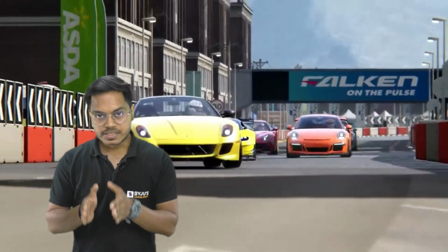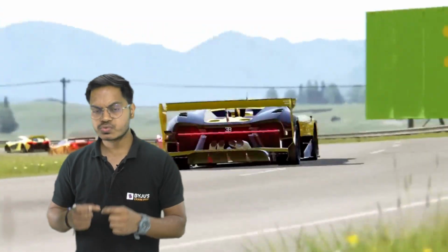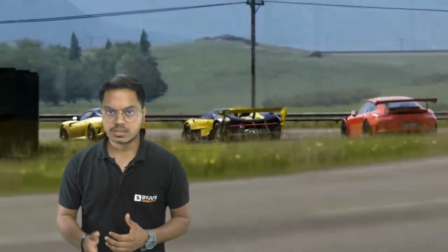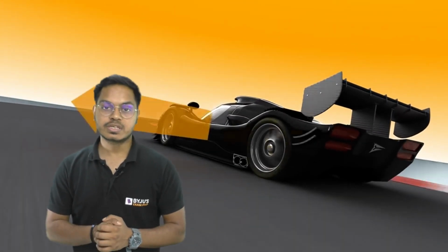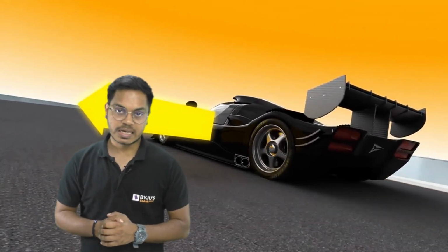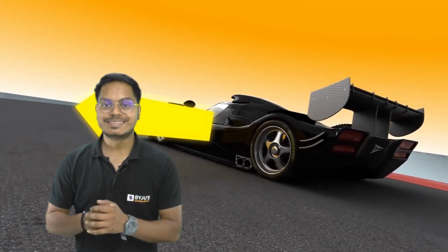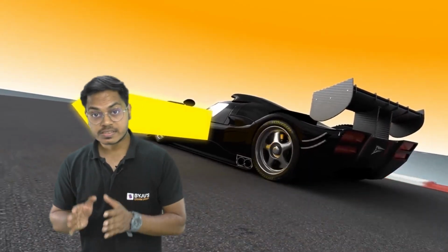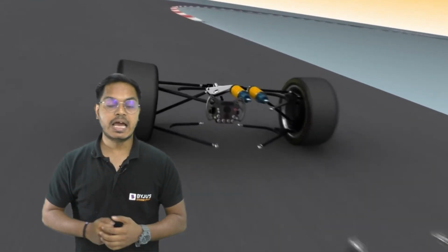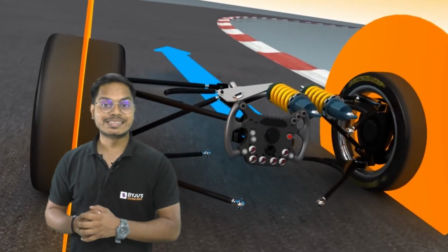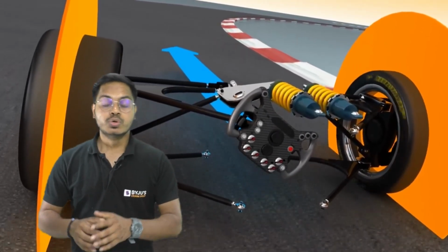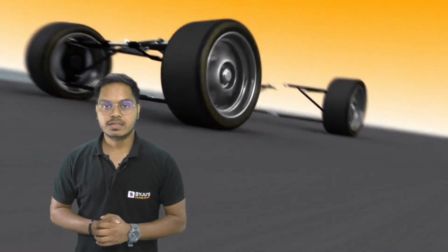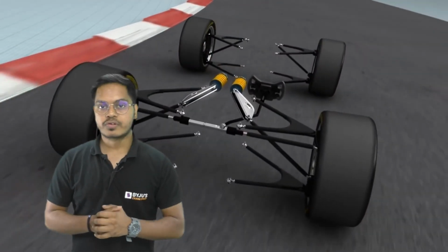क्योंकि जैसे ही कोई भी कार, as soon as any car takes a turn, whether left or right, it actually experiences a force, and that too opposite to the center of the curve, and that force is called the centrifugal force. Now this centrifugal force has the intensity and the capability of either skidding the vehicle to the outer side of the curve, or, you can say, overturning the vehicle towards the outer edge of the road.